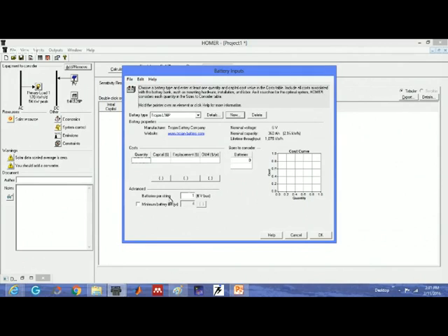Now I will decide the batteries per string. I will decide the bus voltage side, right? Let's say I take batteries per string, one battery is 6 volt. I'm just taking 20. So bus voltage will be 120 volt. So there will be 20 batteries per string. So 20 into 6, the bus is 120 volt. Bus voltage is 120. This is the only factor where we talk about the bus voltage. In one string there will be 20 batteries.